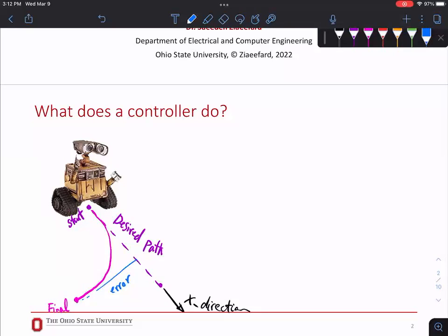So two problems, and these two problems need two controllers to fix them. Same system, two problems, two controllers. All right, so what could cause the problem of moving on the curve? More of the system. The wheels not moving at the same rate, right? They're not spinning the same. So the velocity of the wheel needs to be adjusted.